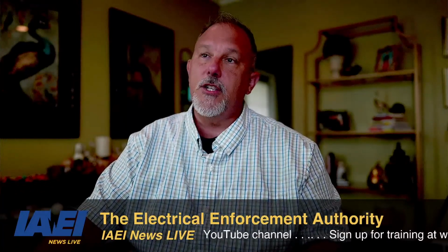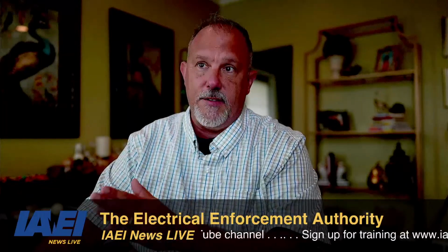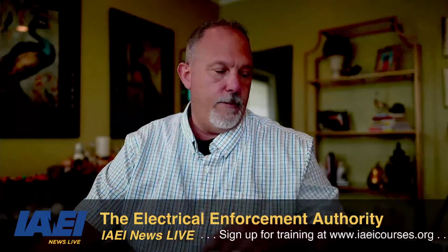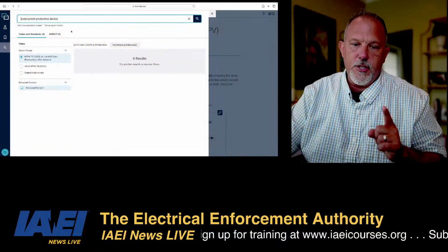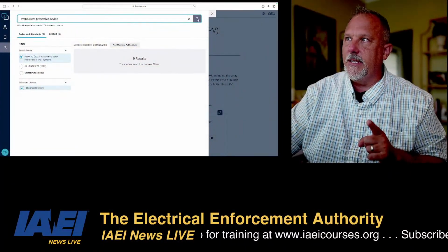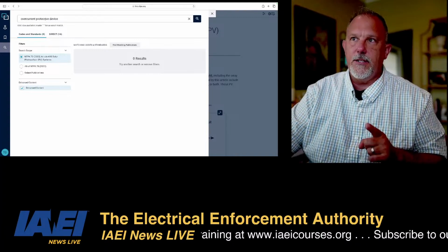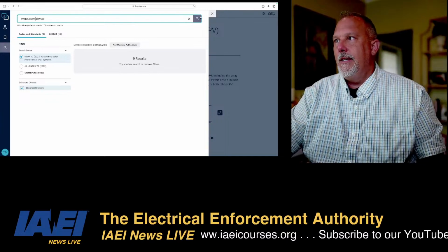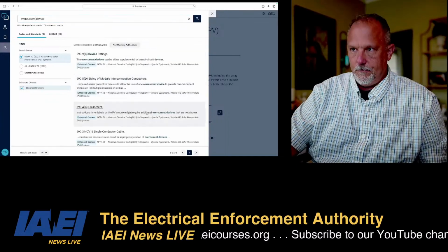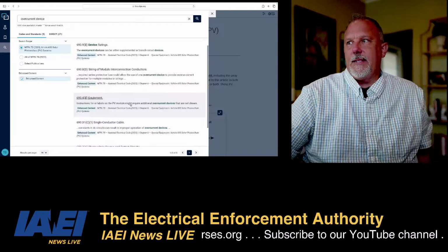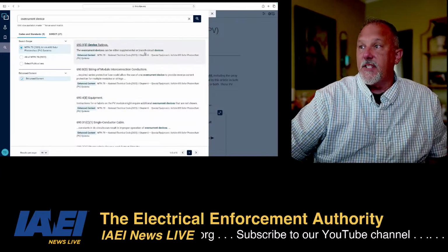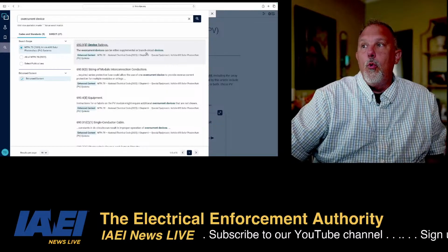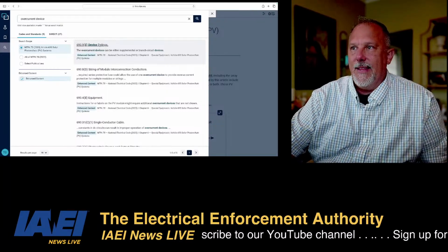it's the cat's meow. So I searched for branch circuit overcurrent protective device in Article 690, and the term is not used. I'm going to search for overcurrent protective device in 690, and it's not found. I'm going to search for overcurrent device in 690. There we go. These are all of the places we have overcurrent devices. Oh, look at this.